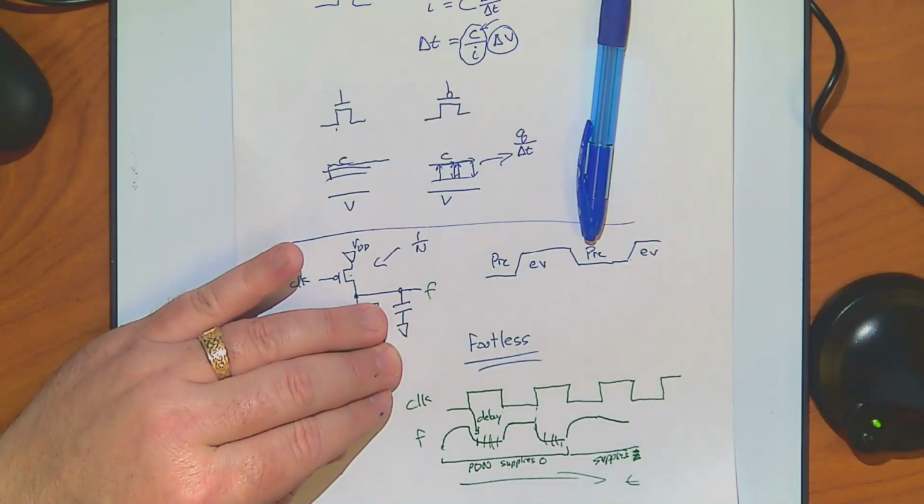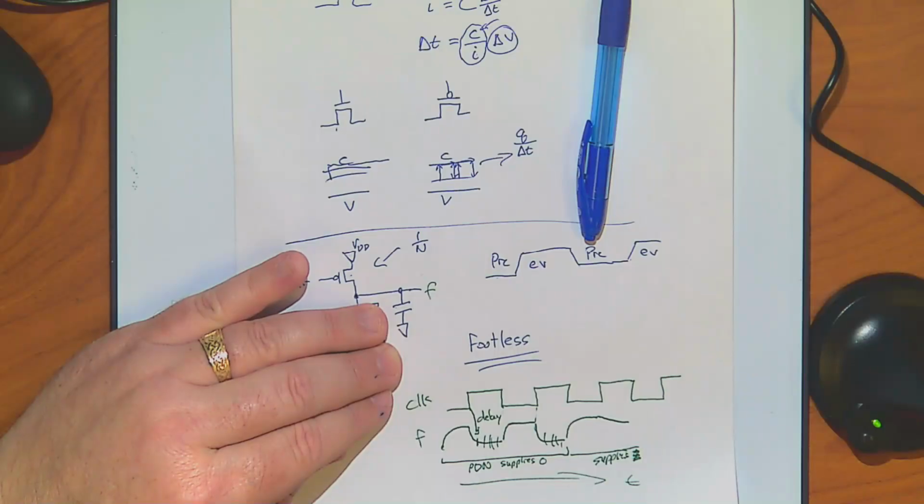Once it's going to get close to that middle uncertain zone between the 0 and the 1, because usually you're a 1 if you're above like 2.4 volts, assume a 5 volt scale. It'll give you a rough idea. The upper half is usually considered a 1. 1 volt and below is usually considered a 0. When you drop to 3.3, usually you have a volt up and a volt at the bottom, and the in-between zone is who knows. So we just try to stay out of it, for safety.